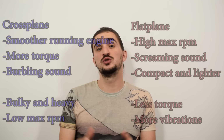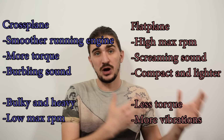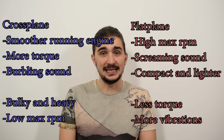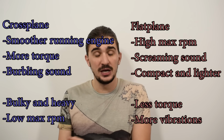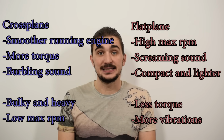Flat-plane crankshafts are also more compact by design, so you can make the engine smaller. A cross-plane crankshaft is typically going to require a larger crankcase. On the other hand, the flat-plane does have its disadvantages and typically it's going to be more prone to vibration when compared to a cross-plane. It's also typically going to make less torque.